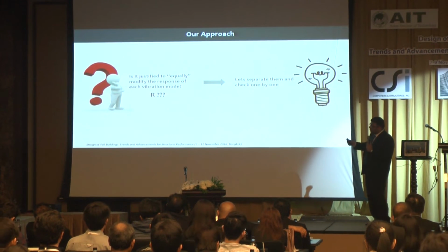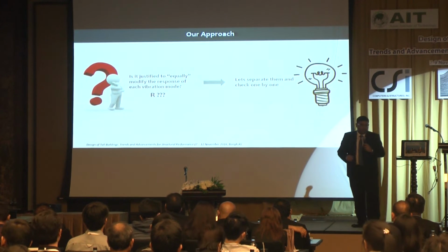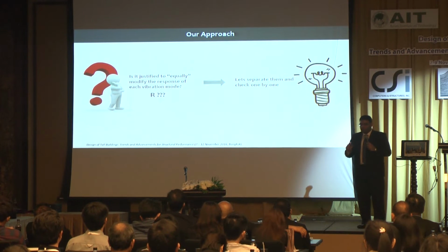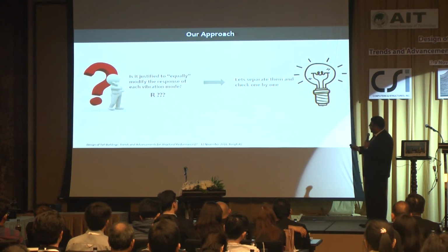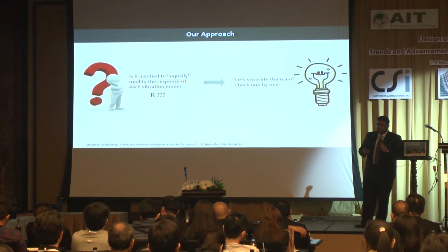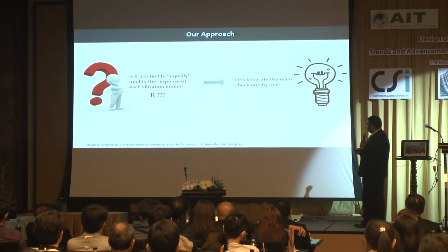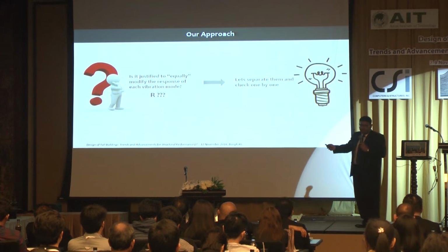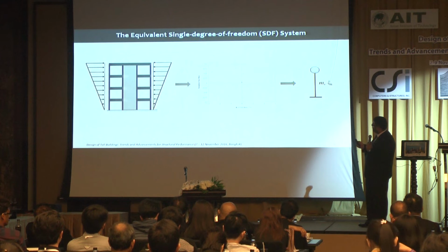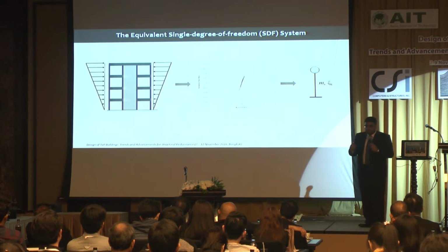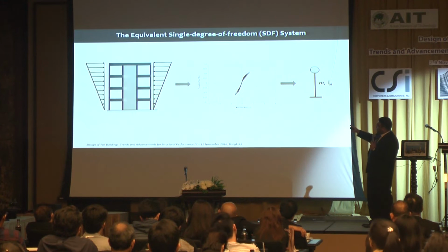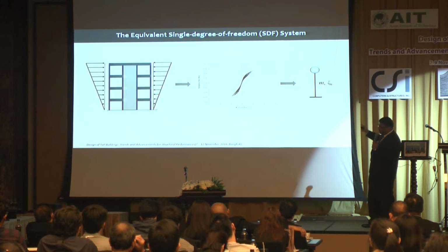So our approach in all this is knowing fully that each mode is different. The response from each vibration mode doesn't experience the same amount of nonlinearity. We simply try to separate them using an approximate modal decomposition technique. In fact, we have tried more than one technique, but I will present one here. The basis of all modal separation techniques is this idea, the equivalent single degree of freedom system idea.